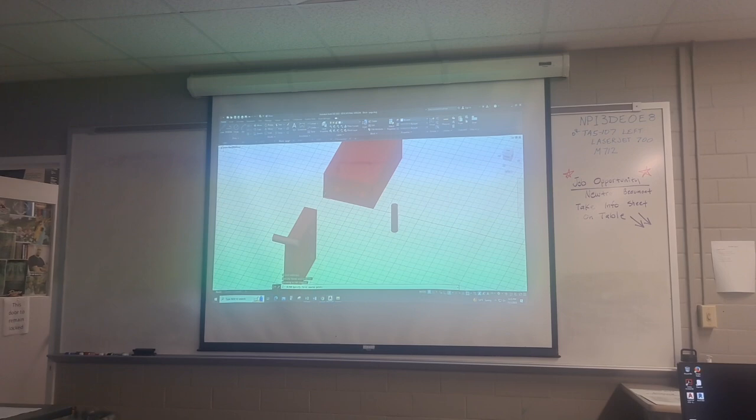Use your 2D or your wireframe if you need to, and also shift right click if you need to force those object snap points on AutoCAD. Like with my 3D pipe, or the pipe that they're drawing in 3D. Once they start drawing this pipe and they've got elbows, T's, reducers, all these different fittings out there, when they hover over a point, there might be 6 or 8 different centers because of the stuff that's in the background, maybe 6 or 8 different centers that it could be.